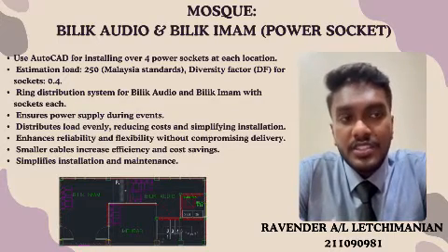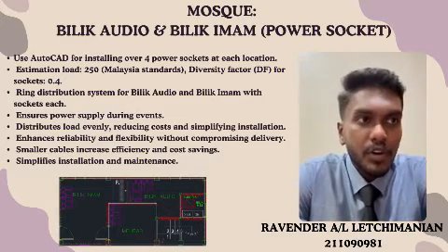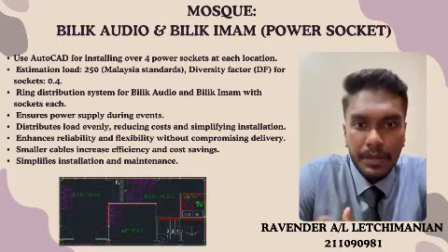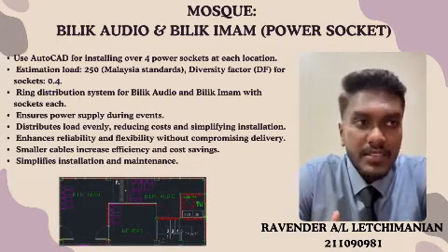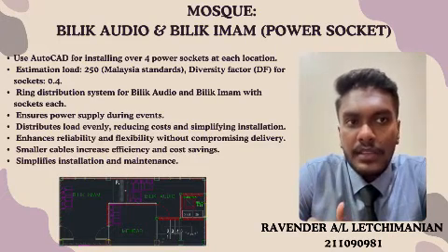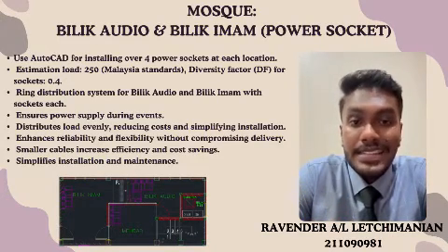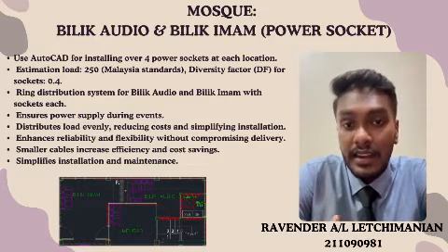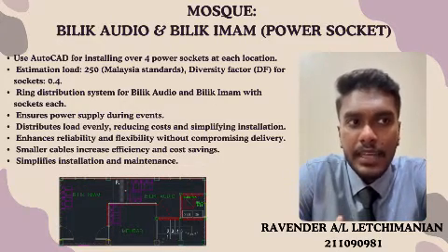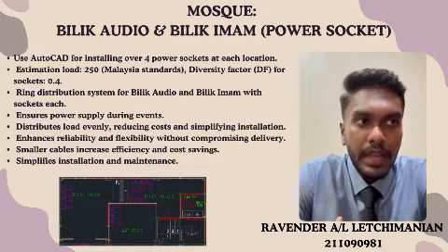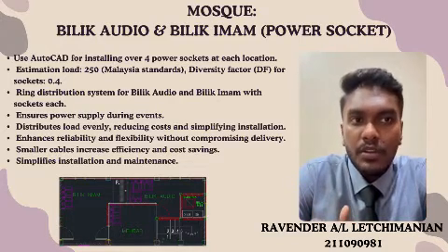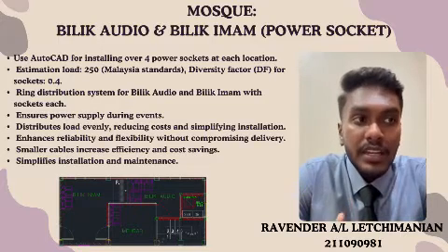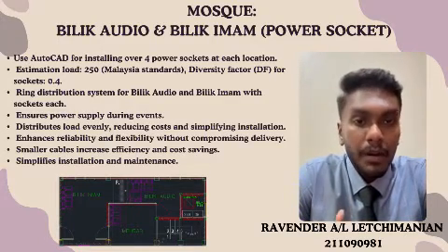Moreover, a ring distribution system allows for the use of smaller cable by distributing the electrical load evenly across multiple pathways. This eliminates the need for large single route cable, thereby reducing the material cost and simplifying the installation. By balancing the load, the system reduces the risk of overloading any single cable, which enhances the overall reliability. The multiple pathways offer flexibility, catering to the varying power needs of the different rooms without compromising the power delivery.